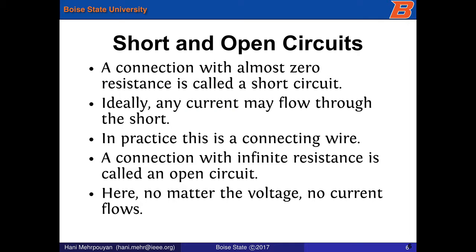So there's the concept of short circuit and open circuit. When we say we're having a short circuit, that means there's zero resistance between 2 points. But that never happens in reality, but we will make that assumption in many of our circuit scenarios. And we denote a short circuit by a wire. So we always assume that a wire has no resistance, which is again not true.